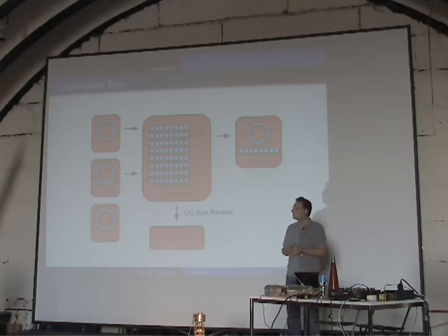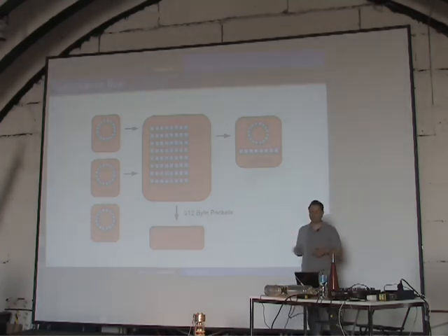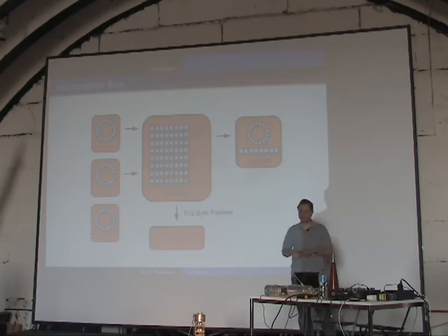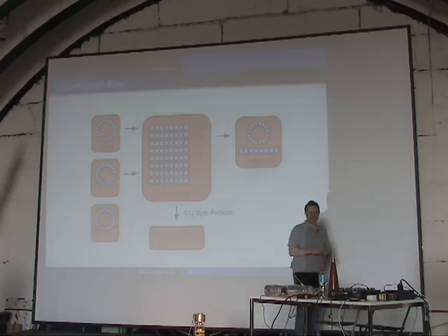Otherwise, I've used it. The problem is that you have data streams with very different data rates, and you don't know what the next system configuration will be, and you don't want to rewrite everything every time. You just want a system where you put an object with a ring buffer, and then you read it out. It does not depend on the data rate. It could be 1 byte per second or 100 kilobytes per second. It doesn't matter, it will work. That's the point. So everything is done in assembler, yes. The board design and the software will be available? You can have it from us, yes. Sure, it's very easy anyway.